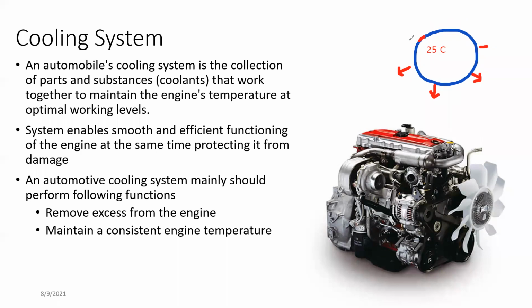So this optimum operating temperature is around 80 degrees Celsius, right? It actually varies between 76 and 95 based on the engine and what sort of materials are used in the components. But usually we say it's around 80-something degrees. So the engine has to maintain around 80 degrees. Maintaining around 80 degrees is the other function. So one is removing excess temperature, but the other is maintaining this operating temperature.